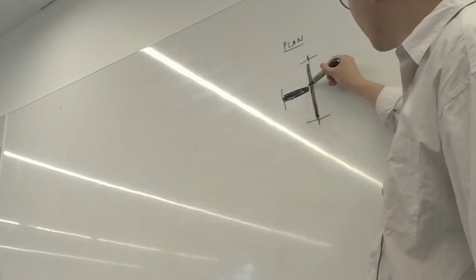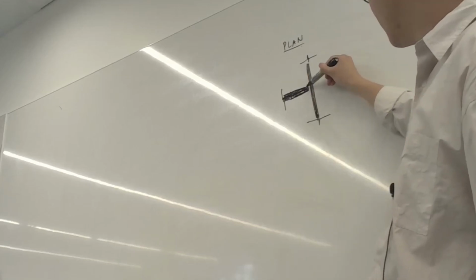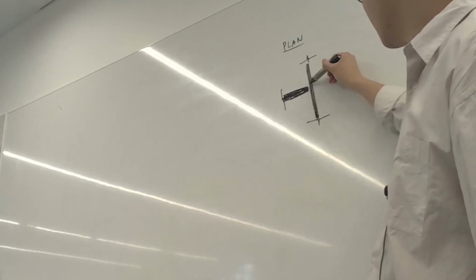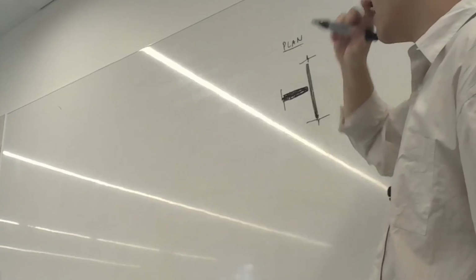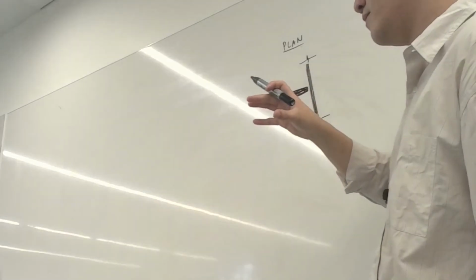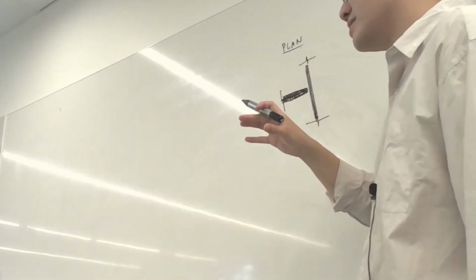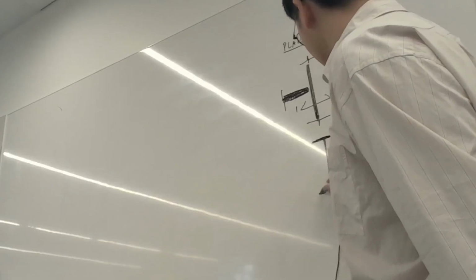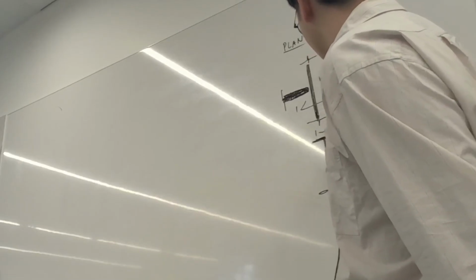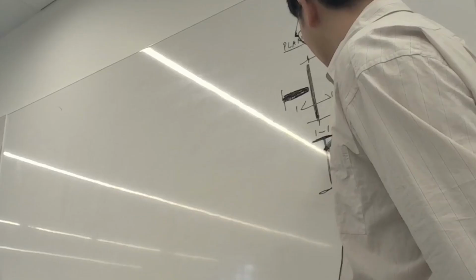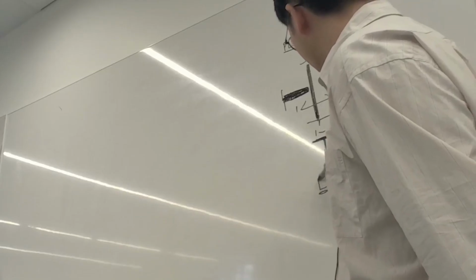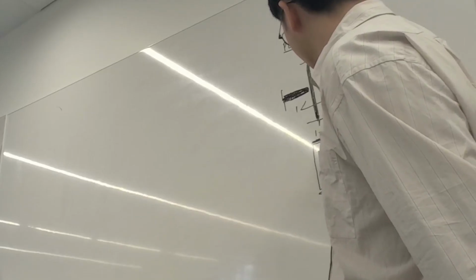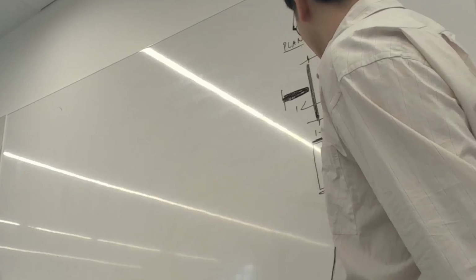And do you see how it ends here? That line stops right there. That denotes a pin connection, which means if I was to draw this section, let's call it section 1-1, that might be a primary beam. So this is section 1-1. And then just a recap from before, this might have some kind of stiffener plate on it.